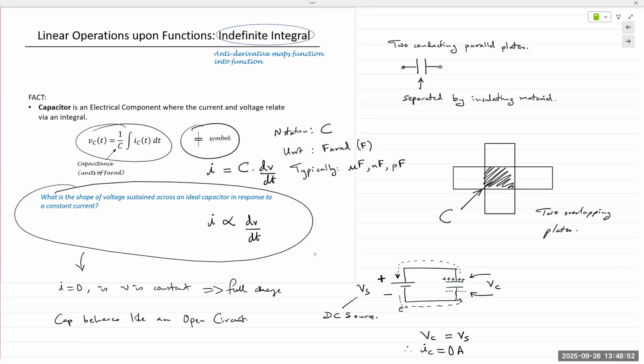Prior to capacitive touchscreens, we had resistive touchscreens, and those required a stylus, a pointed stylus. The reason we required the stylus is because they were resistive. Anytime you touched it with a finger, you had to press down. The sharper the touch, the easier it was to change the resistance of that screen or the sensing layer. When the resistance changed, the position of that touch would be processed, and you would have a touchscreen.